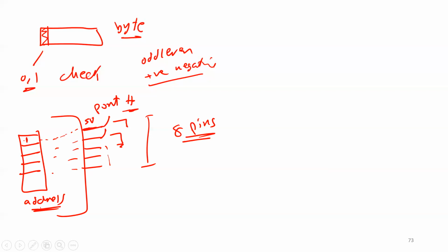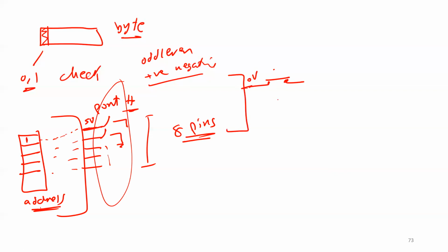So in this case, by the way, I'm gonna design the external circuit so that, as you will see later in chapter 3, if the switch is connected, you are gonna put 0 volt here. And if the switch is open, you are gonna put 5 volt here.